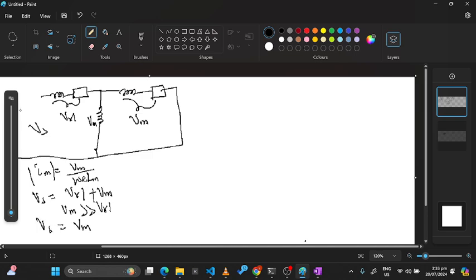Vm. Is that okay? And at the point where Vm is very high, that means omega E should also be what? Very high, in order to maintain this. Remember, this is kept at the rated value. Is that okay? So then we are saying at very high values of Vm and omega E, Vs should be equal to Vm.